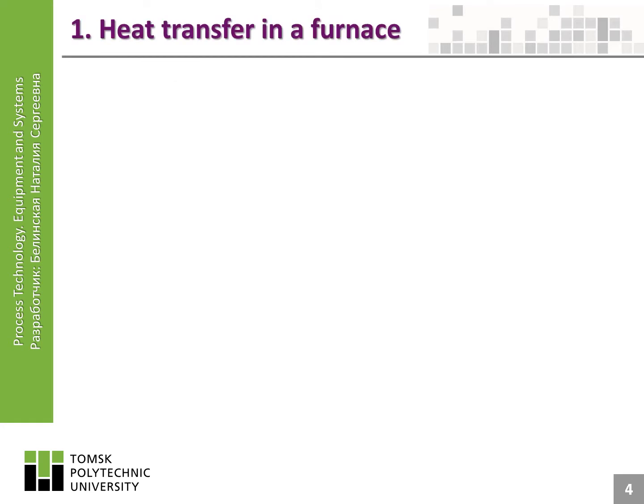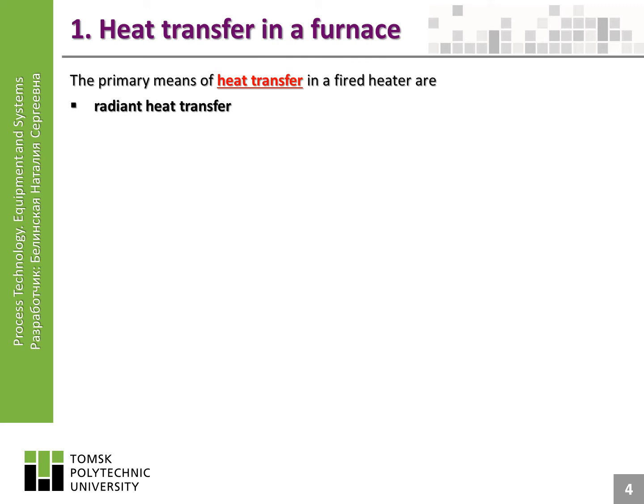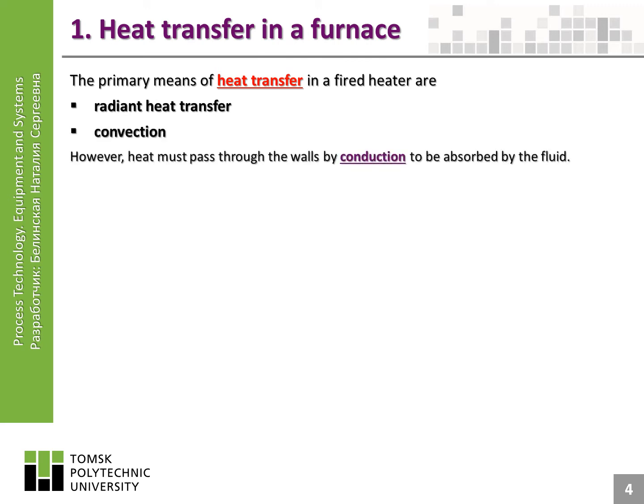Heat transfer in a furnace. The primary means of heat transfer in a fired heater are radiant heat transfer, convection. However, heat must pass through the walls by conduction to be absorbed by the fluid.